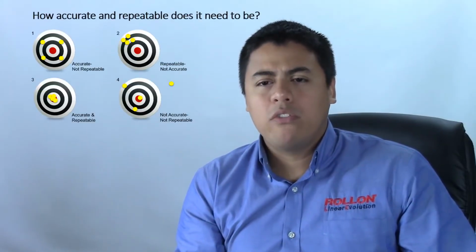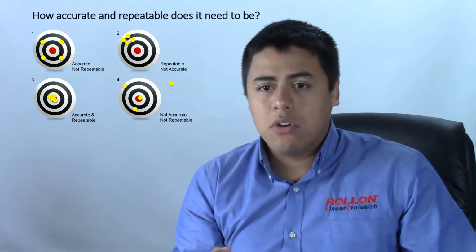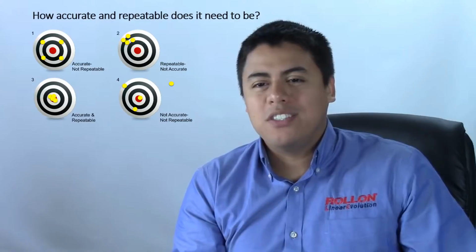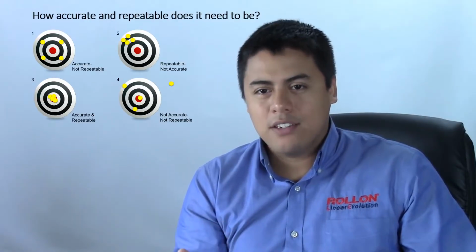For the first letter, A, represents accuracy. By accuracy, we not only refer to positional accuracy, but also system repeatability, as well as general mechanical accuracies such as parallelism, flatness, and straightness, if applicable.